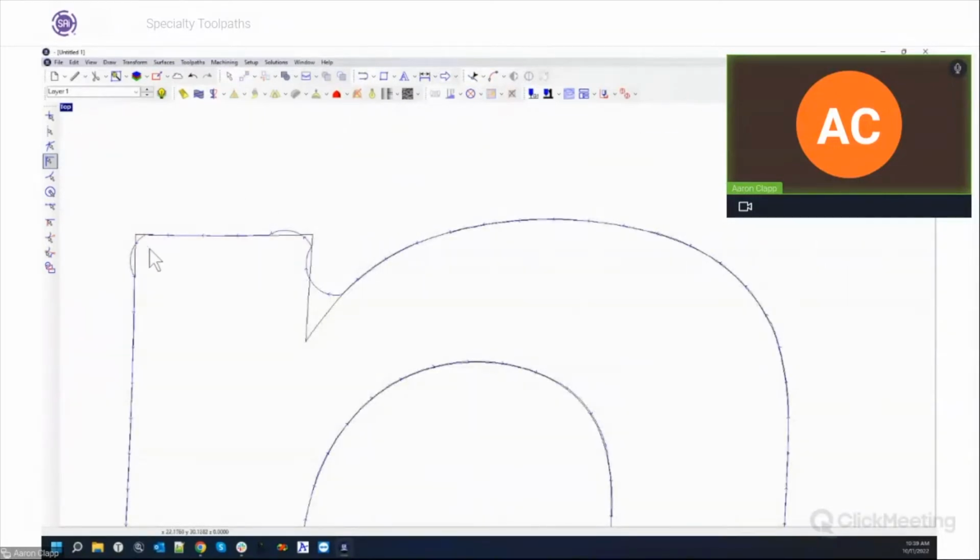This is an over-exaggerated example, but you can see where it's cutting off the edge in order to avoid some of those cases where the drag knife is going to get in this corner and dig into the material, because even with the drag knife, you're always going to have that rotation of the blade happening as you drag it. When you get into a corner like that, it can really cause some issues. And if it's causing tearing or other problems, perhaps applying a small radius to avoid that little corner would be a better option.